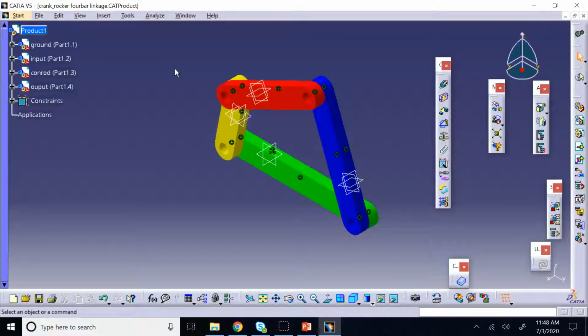So one thing was modifying an existing component. Two is, what if I want to now add some pins that go inside these holes and make it more realistic, right? In real life, they are connected by pins, right? So let's make a pin. You know, the thickness of the pin has to be what? 20 units, because each one of them is 10 units thick. And then the diameter of that should also be 10. And I need 4 of that, right?